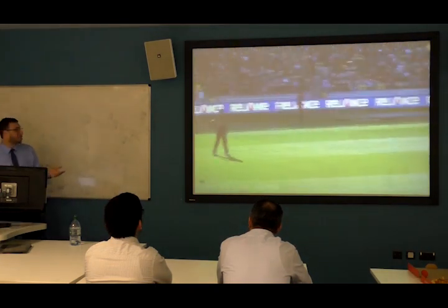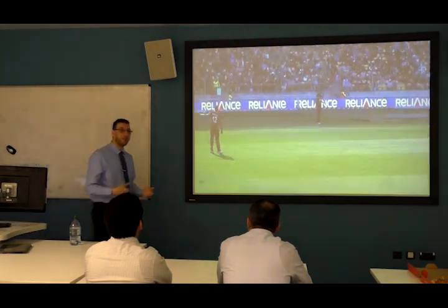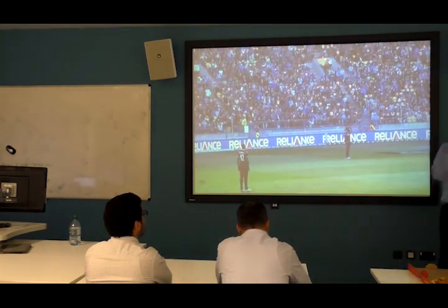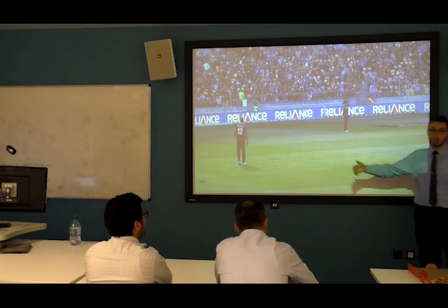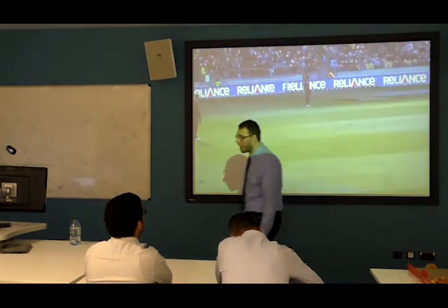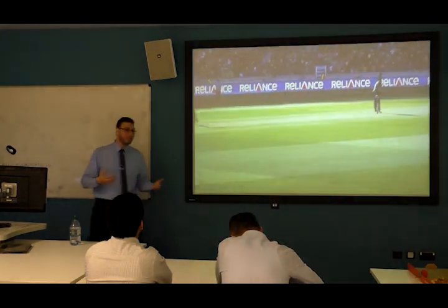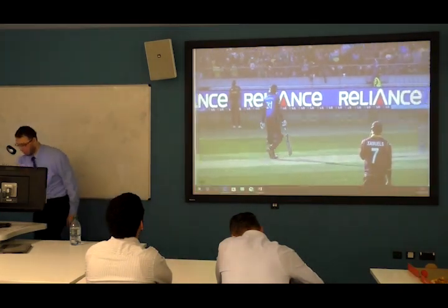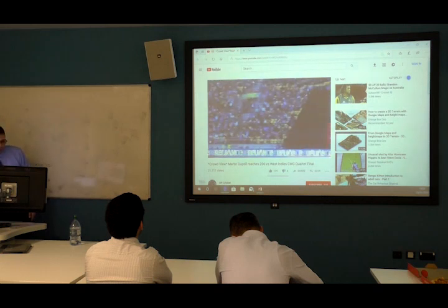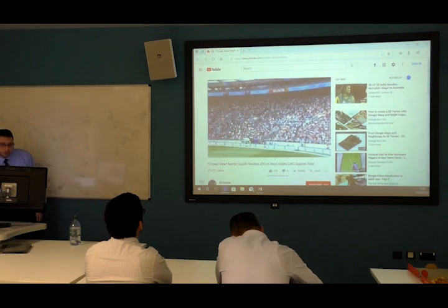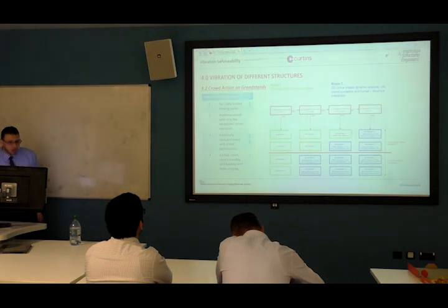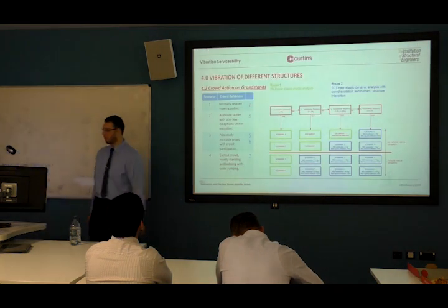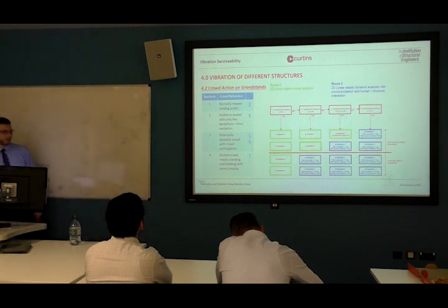Some jumping, but not a lot of dynamics. When we talk dynamics, we have to think about periodic things. Someone jumping is not a dynamic towards a huge grandstand. They need to be like, whoop, whoop, whoop, whoop. Something really periodic to cause some motion to the structure. So this is scenario 2. Once you get scenario 2, you have to think about the dynamics of your grandstand.